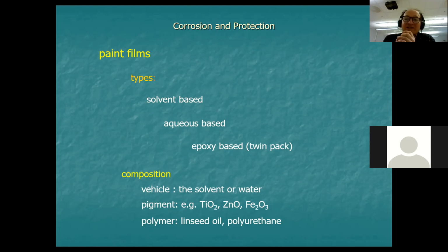And these work slightly differently in the sense that the water, which is the solvent, just evaporates. It doesn't do anything. It just disappears, leaving behind the binders and plasticizers, which are the body of the paint.